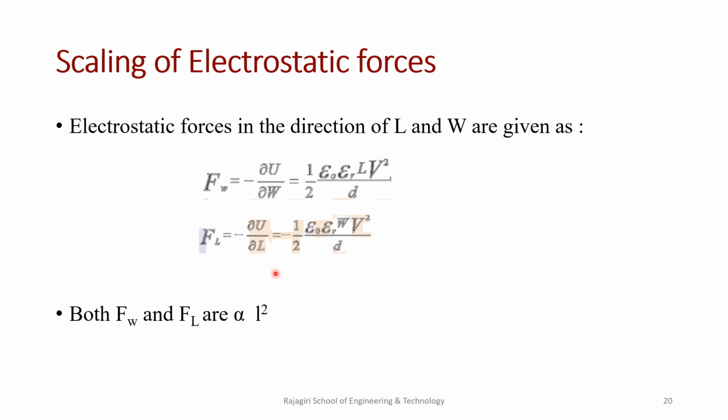When calculating the scaling of electrostatic forces Fw and Fl, we also obtained it as both proportional to L square. So the same inference as in the previous case is existing here also. That is, a 10 times reduction in the linear dimension will cause 100 times reduction in the electrostatic force.